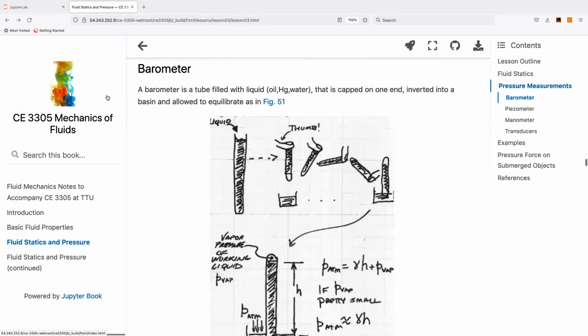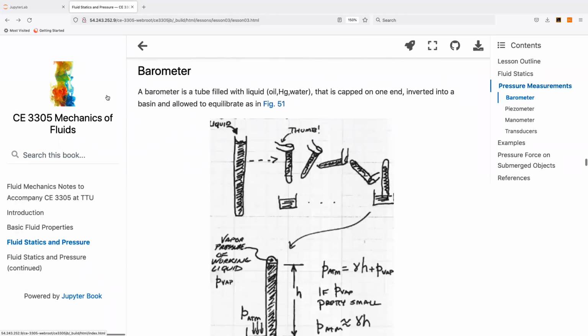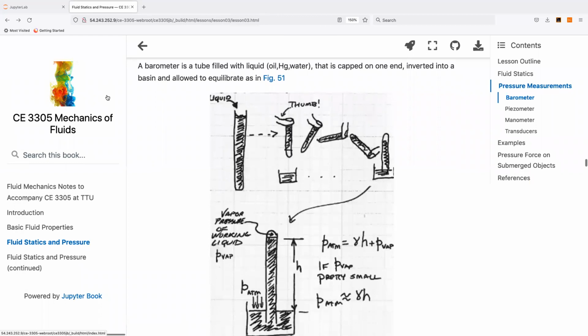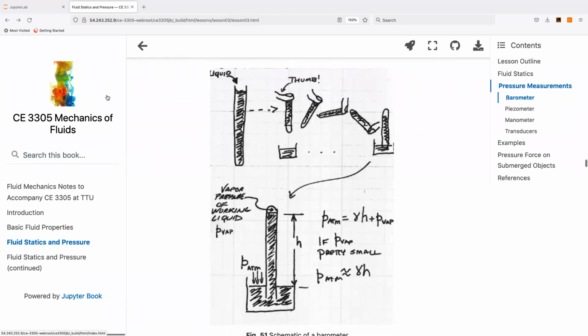The last one is pressure transducers. I think I have a picture of that. So let's suppose we wanted to make a barometer. We want to measure atmospheric pressure. So there's a couple ways to do it. The smartest would be to go on Amazon and just buy one, but not all of us are smart. Some of us would just take a pot that we find in the kitchen, fill it with water, probably put food coloring in it so you can see what's going on, and then find a glass tube. It's shown there. Put the colored water in the glass tube, fill it all the way up until it's overflowing, and then put your thumb on it, or anything that you have that's big enough to fill the tube.